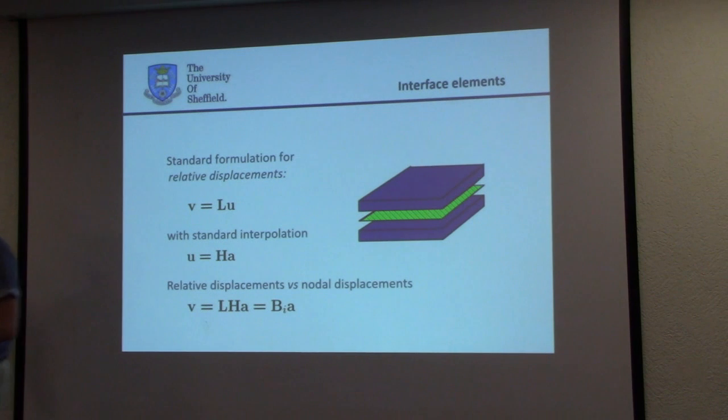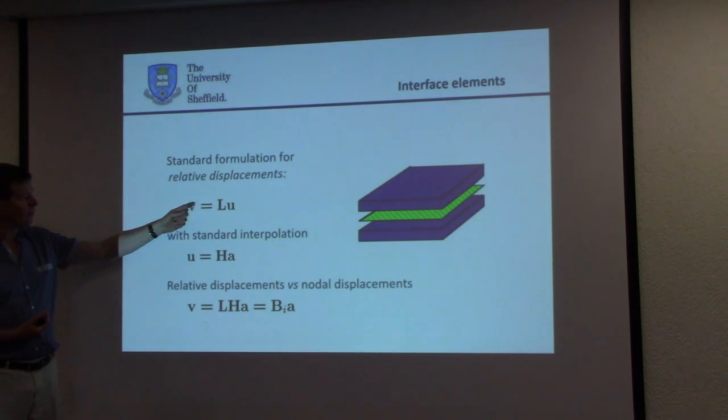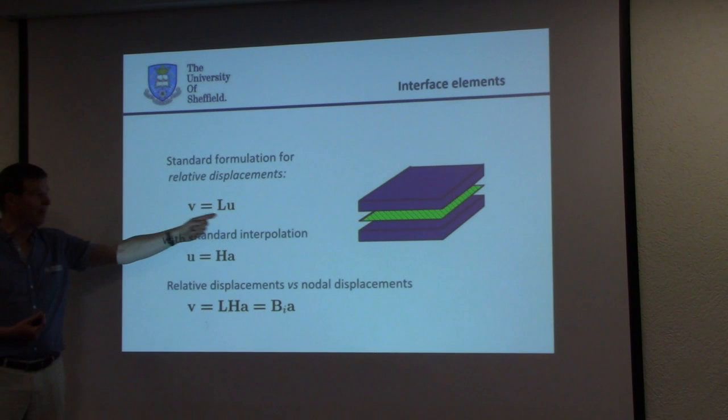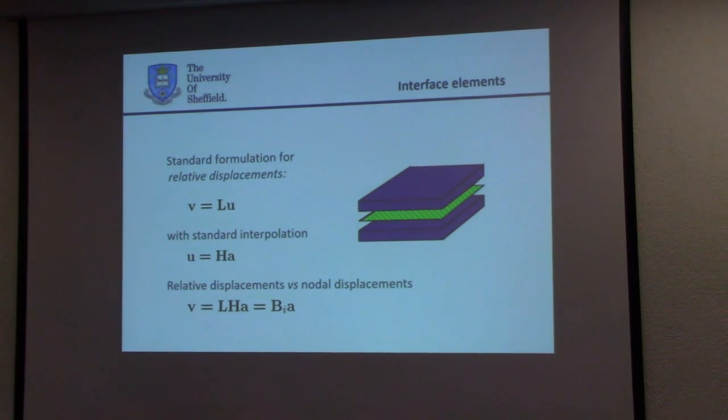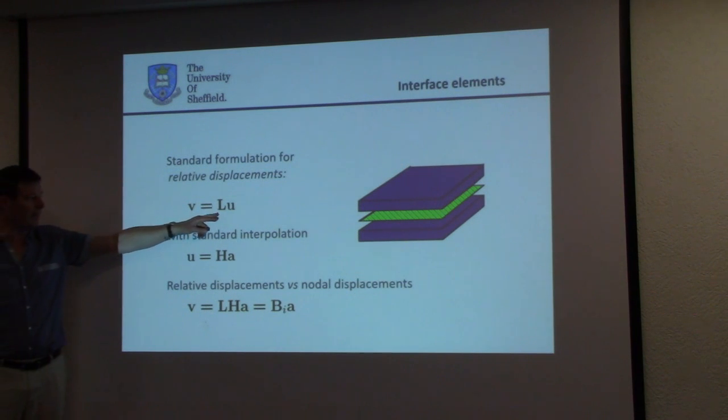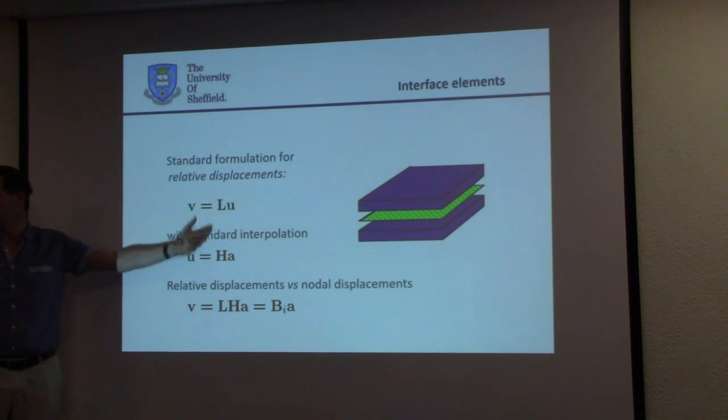and therefore you bring V also back to the nodes. Just to confirm, L is like both sides continuous operator. The input is continuous, output is also continuous. But for H, the input is discrete and the output is continuous. These are continuous operators. Compare it with strain, which is a matrix with differential operators times a continuous displacement field. Just think in your head as epsilon is L times U, where L has ddx, ddy, etc. It's just the strain operators.